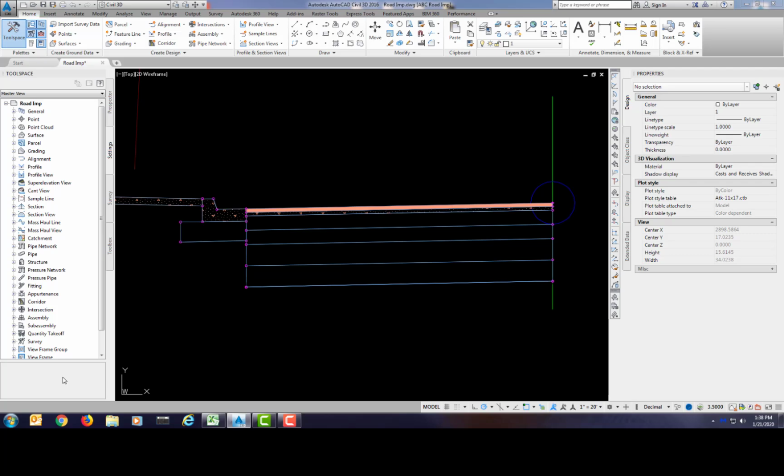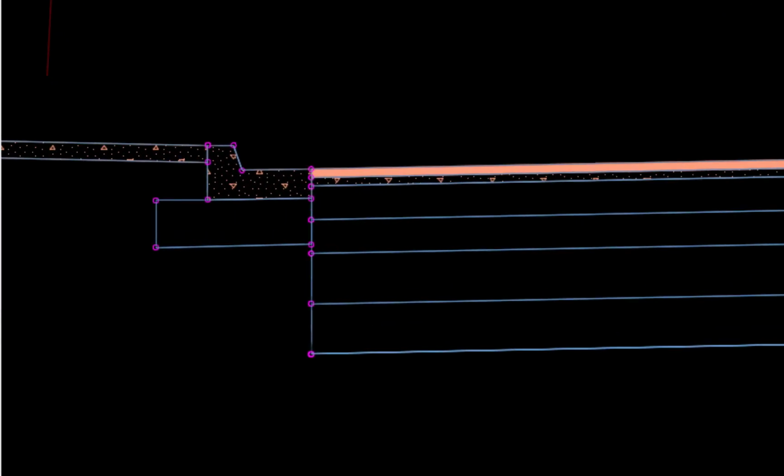Okay. The curb subassembly default parameters are for a 6-inch curb with an 18-inch wide gutter and are left as is, except for the curb subbase section, which is generally constructed concurrently with a pave 3 aggregate base. As such, the right bottom marker of the curb subbase section must be coincident with the left bottom marker of the lane pave 3 aggregate base section.